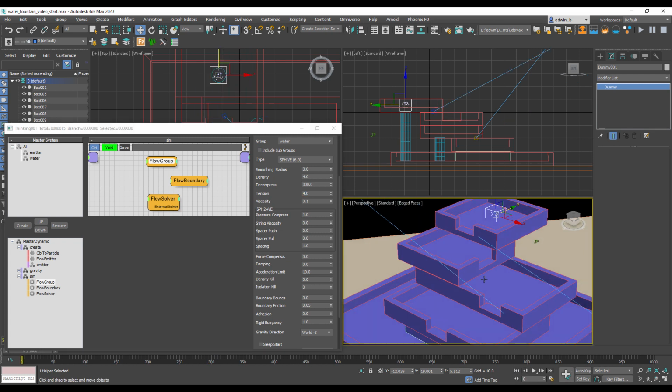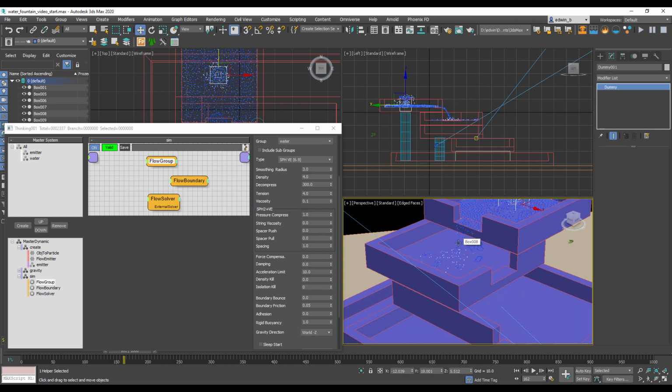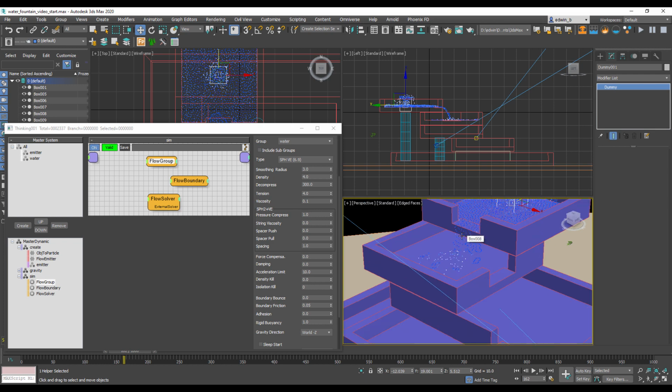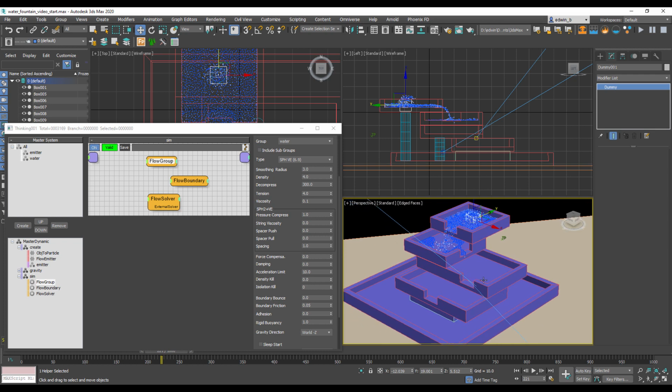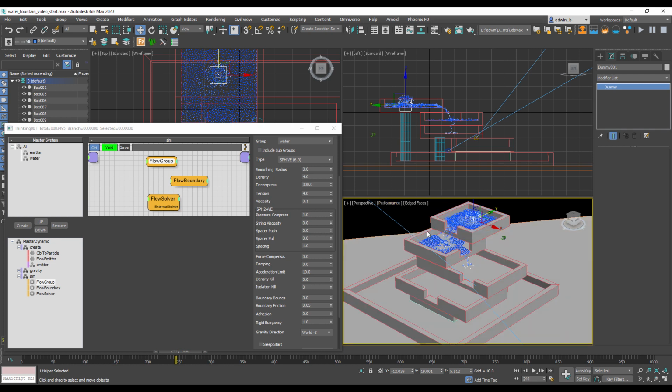I'll put this pretty high because it's a smaller scale. So I want to see the droplet building and puddle building. And we can see now this nice tongue, this tip that is created through the water tension, which looks much better. It's hard to see. I think I'll change the display mode in a second, but yeah, we can see it's nice surface tension.